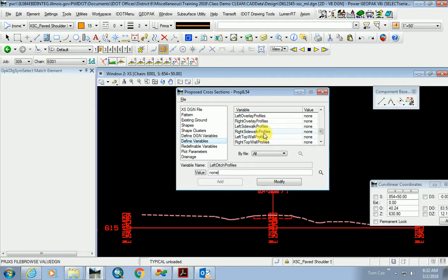And when you're using this typical, I'd highly recommend you print out, hit that description button, read the instructions, and you'll see all the things it's capable of doing. If you have an urban job and you have sidewalks and you drew that sidewalk in, it will automate the process of drafting the proposed sidewalk with the cross section. Like I said, curb and gutter, swales in between the curb and gutter and the sidewalk. It'll do everything that you're going to see here, plus more.